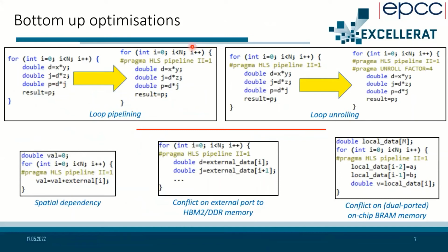We unroll our loops to give us effectively vectorization, but then also below the red line, we've got some negative aspects that can really impact our performance, where, for instance, we're not getting a new loop iteration processed every cycle and we're losing performance. And the reason for really showing you this is what can then happen is our code moves very substantially from the CPU version to then the optimized FPGA version, playing these games to keep that data flowing in order to get the performance.